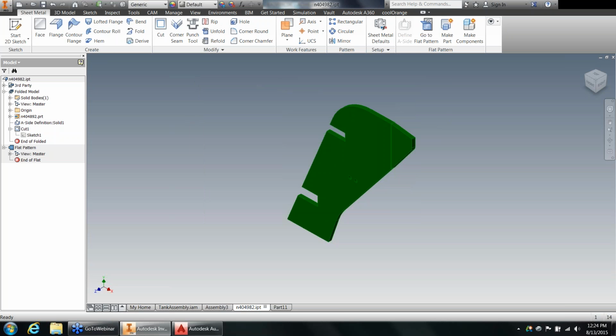where I want to gain control of these models, then you should be using the same methodology that you were using in the past, right? Just hard importing these files and then making any modeling adjustments using your standard modeling changes. If you want the SolidWorks users to be able to control their models parametrically and you're simply seeing those changes live or seeing those changes after save, then you would want to use the referencing functionality, right? That creates that association and it's not breaking or making dumb solids.